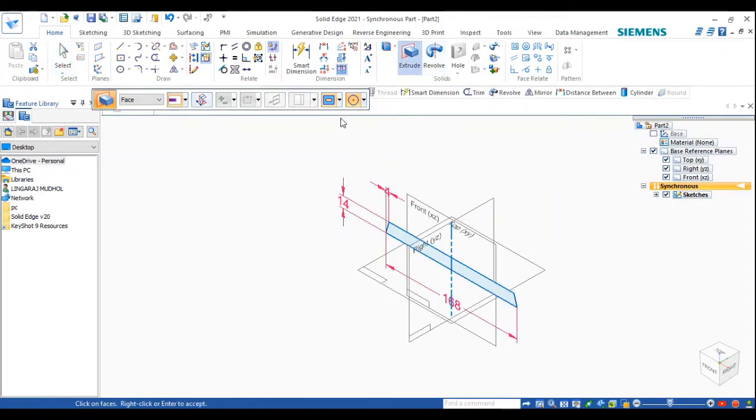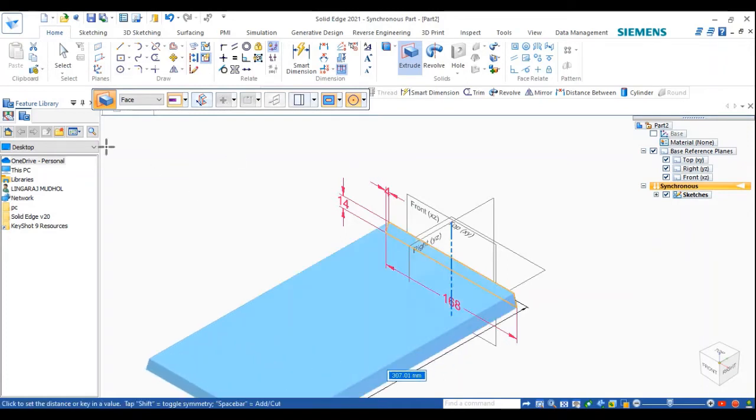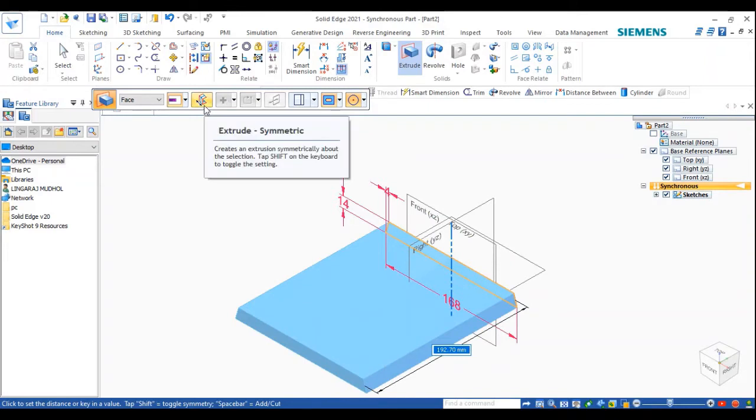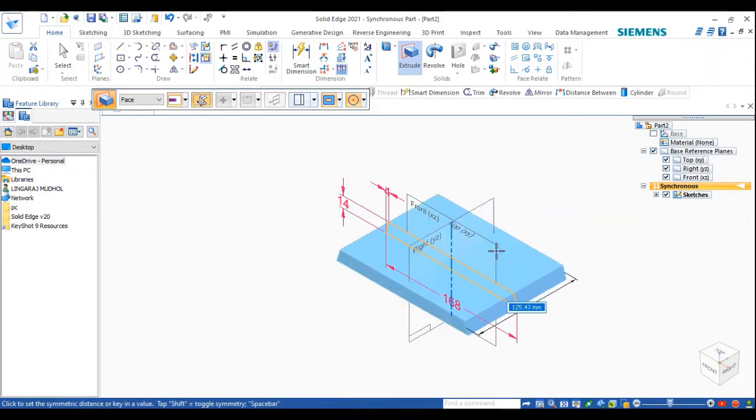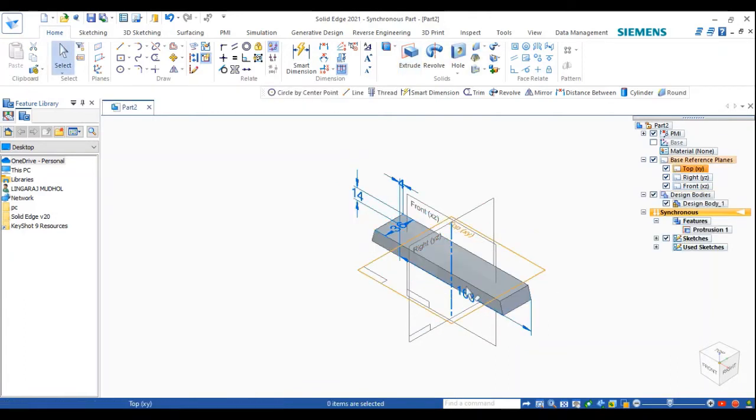This also means the protrusion. In other words, first select the object or the plane or the diagram or the sketch which you want to protrude or extrude. I'll select this one, right click. See, this is only on one side. There is an option called symmetric here. Click here. See, you'll get it on both sides. So the width is 36 mm. See, you'll get like this.